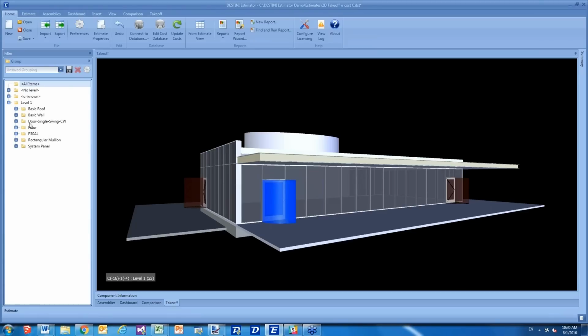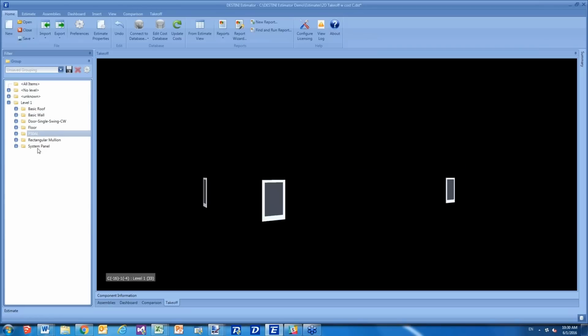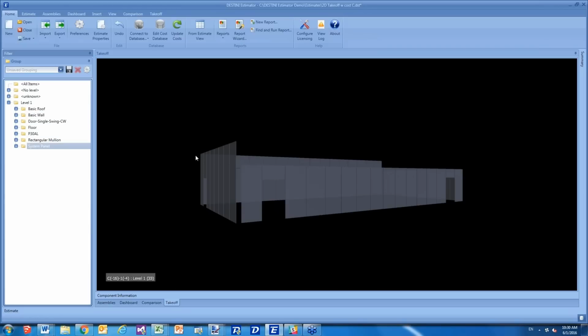We can keep this costing, even though right now there is no costing applied to this model. Maybe I'm going to leave in master format level 1. So we'll have it layer, then family, then master format level 1. Right now, you can see that my filter view is now broken down by the layers in the model. The way that this workflow would work is that the models are broken down by information that typically the author would organize off of. So Revit family element and layer would be traditional properties that you might look at when trying to break down the content in this model.